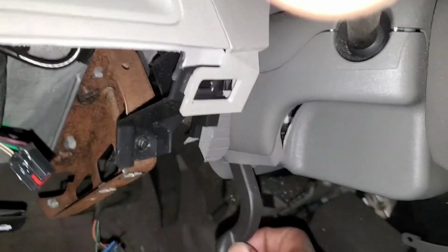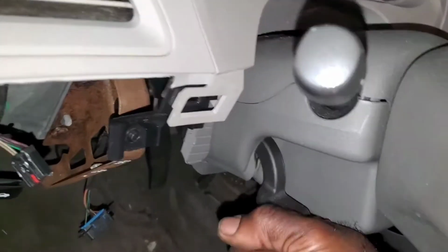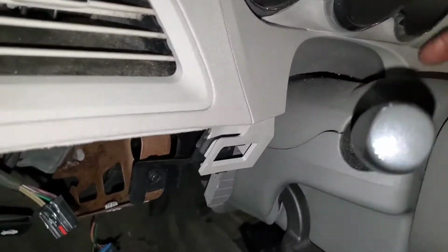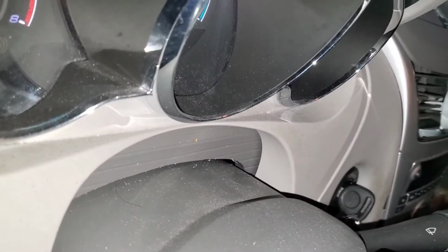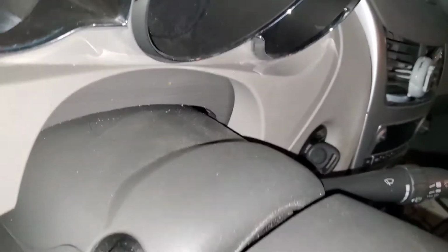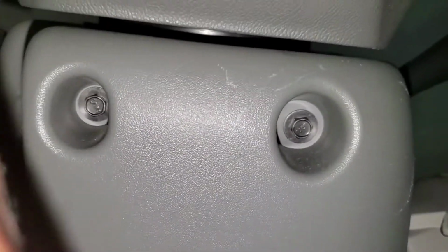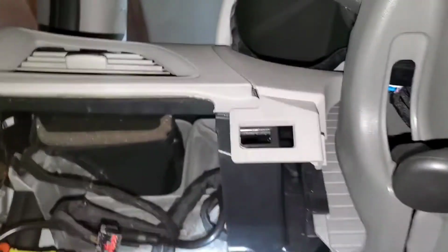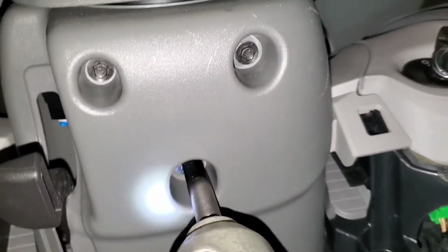So I'm going to start disconnecting connectors next. All right, and so use the tilt lock, release it, bring the steering down a little bit, and then pop. They say the steering covers pop loose. I don't know how that is, so I'm going to try that here. Make sure there are no screws. Let me look around. Yeah, wouldn't you know it? Guess what's under here? 3 7s. 21. All right, let's get them out.